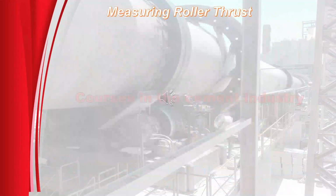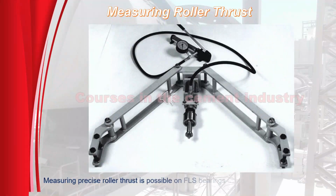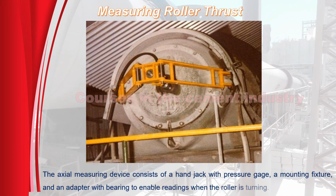Measuring roller thrust. As shown in this figure, measuring precise roller thrust is possible on FLS bearings using this axial measuring device. As shown in this figure, the axial measuring device consists of a hand jack with pressure gauge, a mounting fixture, and an adapter with bearing to enable readings when the roller is turning.